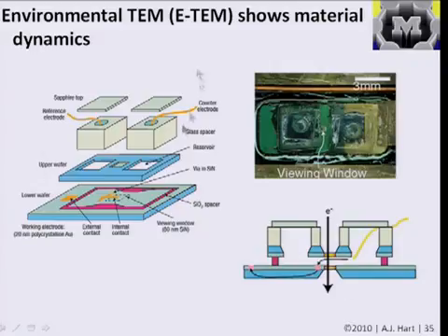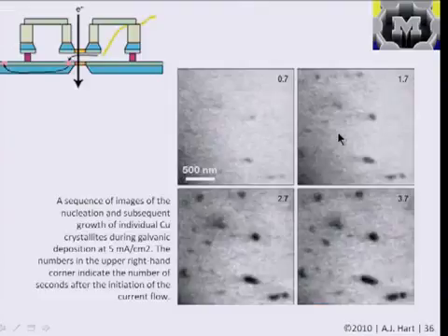And this was from a few years ago, and there are more sophisticated, or you could say neat-looking, designs since then. By connecting a couple of silicon wafers with thin windows in them and a couple of electrodes, through a combination of manual assembly and microfabrication, they created this little cell which they put on their sample holder in the TEM and passed the beam straight through this window. And we're able to see. The goal here was to observe the electrode deposition or electrochemical growth of copper nanocrystals.